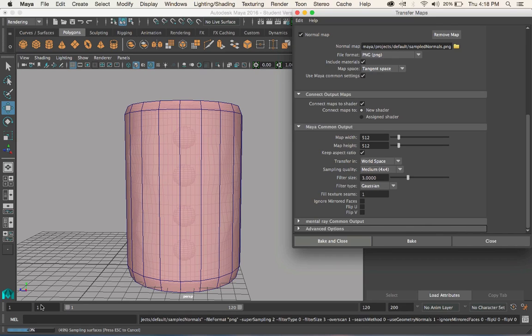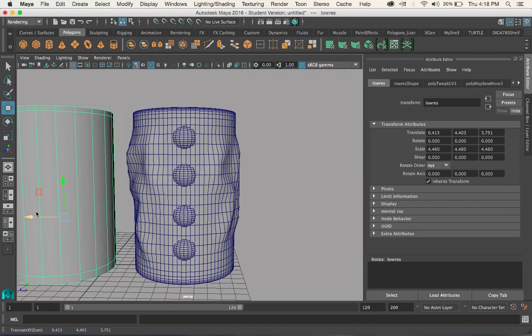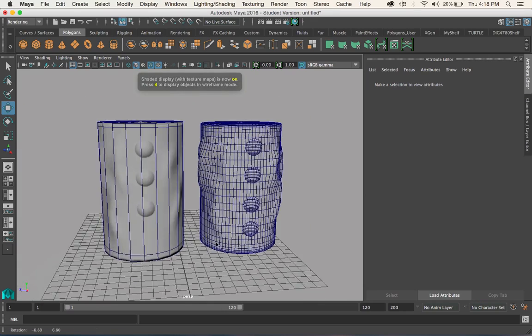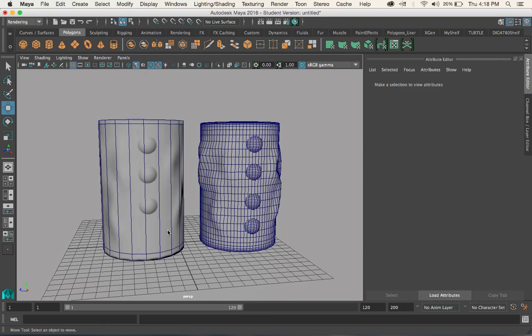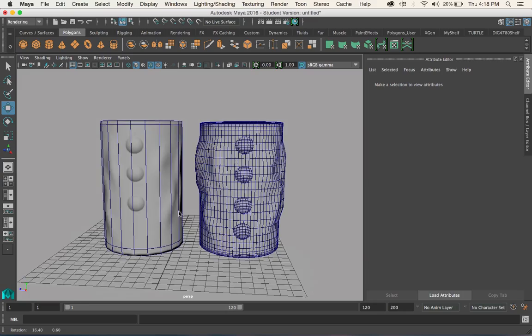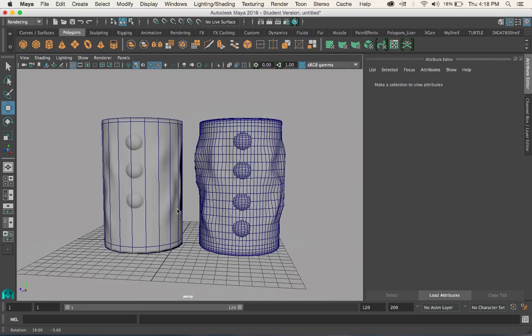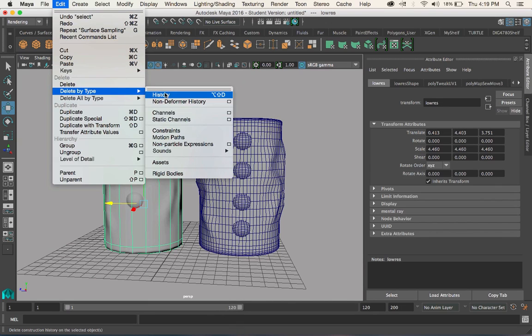And you can see it here at the bottom, it's processing. And what this is doing is taking all the geometry to the high-res objects, and it's going to turn them into a bump map for the low-res. So let's move this aside now that it's completed and hit 6 on our keyboard. And voila, you can see that. Now, I must have accidentally forgot to grab the lower sphere here, hence why I don't have it. But what happens is it's perfectly flat, as you can see, but it gives us the illusion of this depth. And what it's created for us is a normal map.